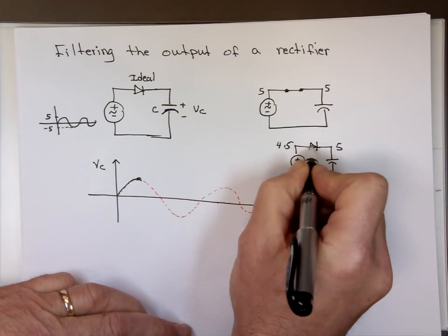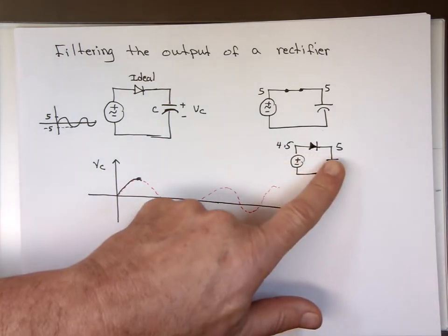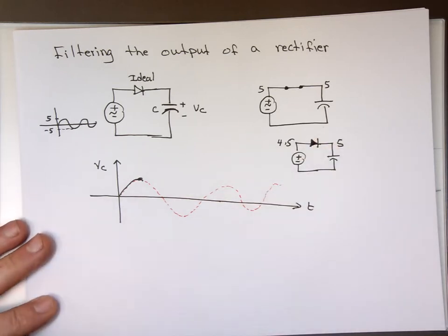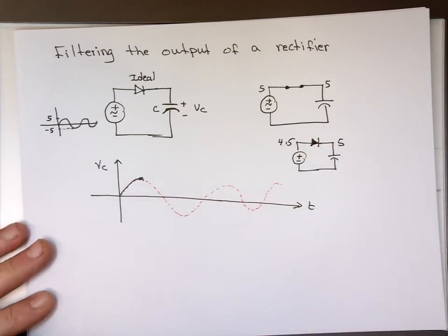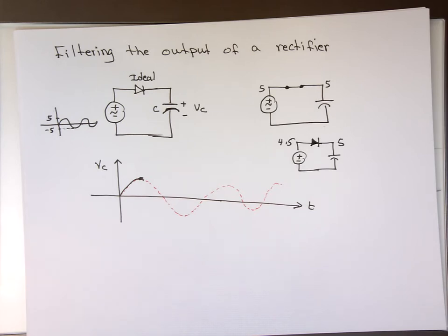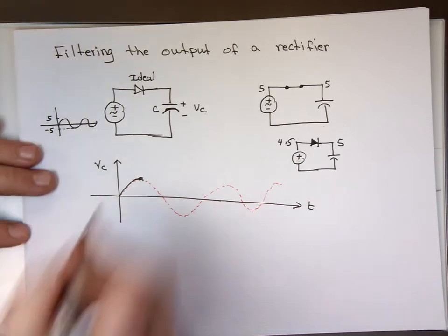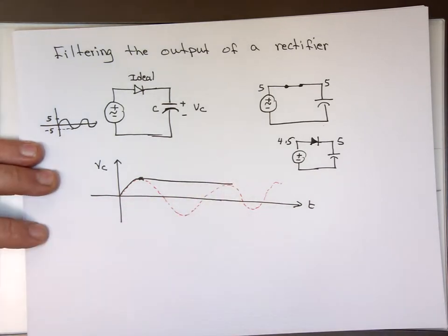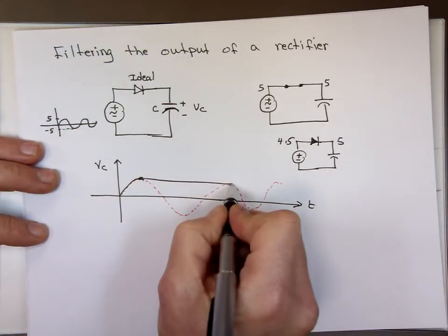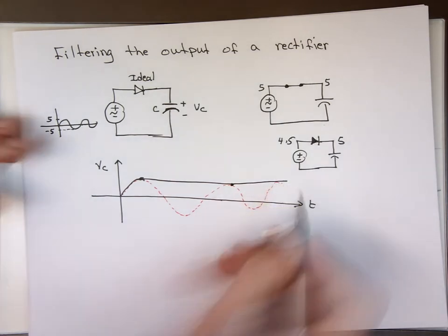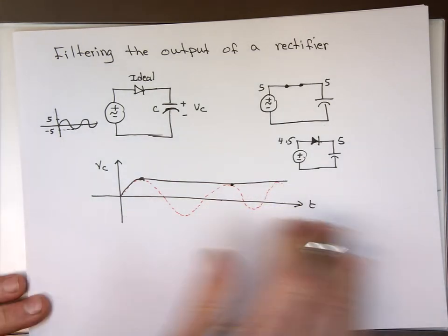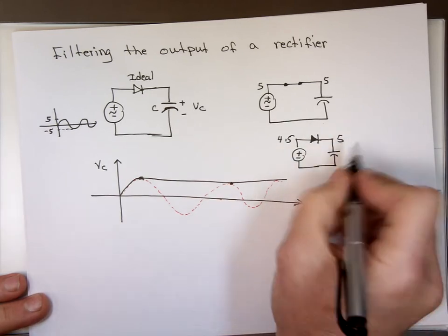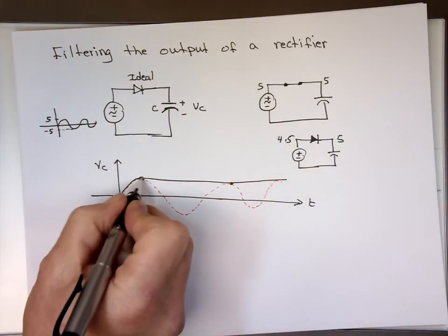What's going to happen to that diode there? It's going to be reverse bias, which means no current is going to flow through it. Well, if no current is going to flow through it, that voltage will stay the same. It will not change. Will stay constant. Right here and constant right there. So once you hit that voltage, the output here, V out, will remain the same, which is 5 volts. If this is 5 volts here.